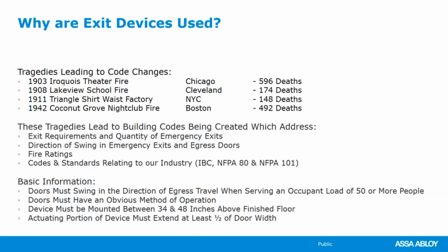And this is where we get into trouble sometimes, with stocking distributors. I was a distributor in my early days, and I've sold 4-foot doors, and I've had people ask, well, do you have an exit device for that door? I didn't stock a 48-inch rail. Well, can I put a 3-foot bar on it? You really can't unless that bar goes the entire width, unless the actuating rail goes the entire width. So it could be a problem if you are trying to use a 36-inch rail on a 48-inch door. So just bear in mind, it could be an issue.